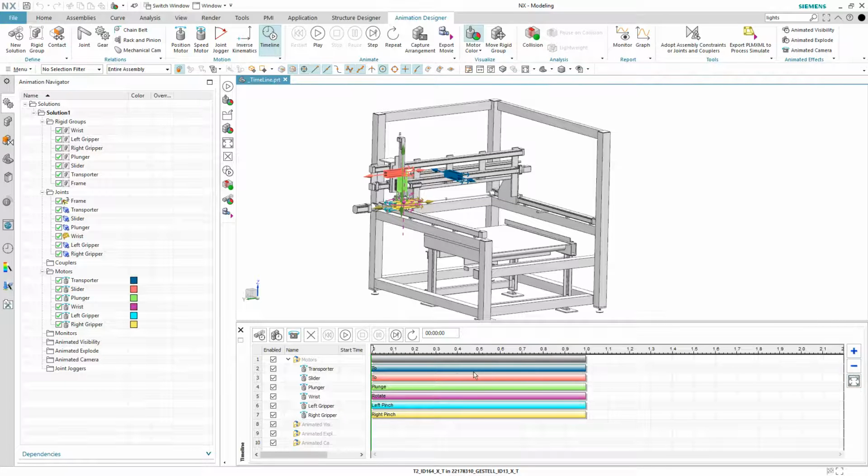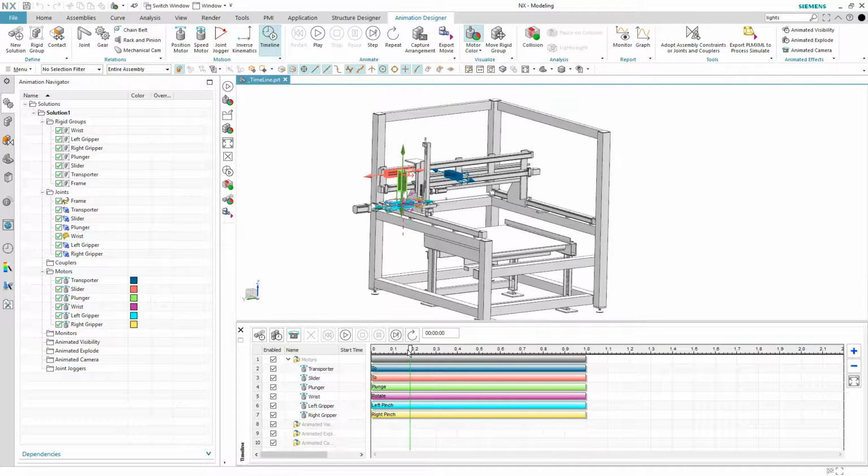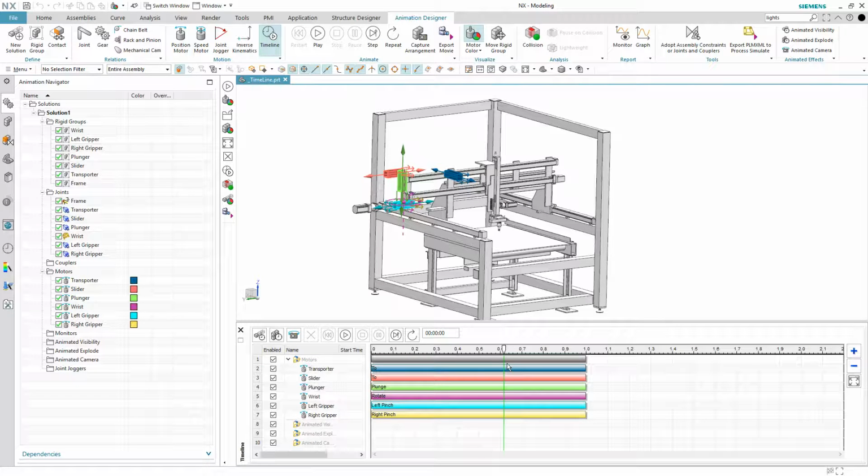If you right click on a time bar here, you can edit it, which edits the actual position motor. You can delete that entire motor, you can cut it, copy it, paste it, and you can actually mirror it as well. There's also an operation for splitting that if your cursor is not at 0 or at the end, you can split an operation into 2.